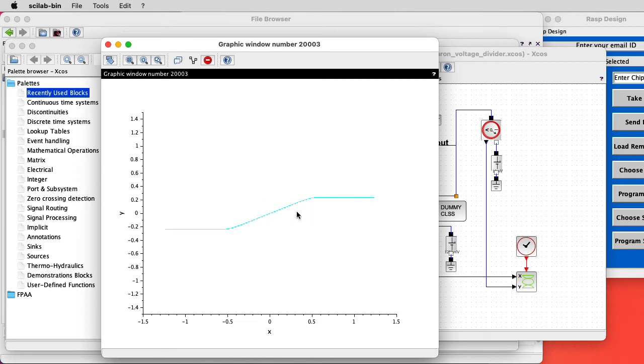You get a hyperbolic tangent nonlinearity if you have MOSFETs that are operating in the subthreshold region, which a lot of textbooks will just call off, but it's actually a useful region to work in. And you get a hyperbolic tangent-like nonlinearity. It's not exactly a hyperbolic tangent if you have the MOSFETs operating above threshold.